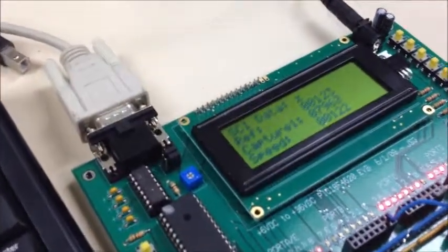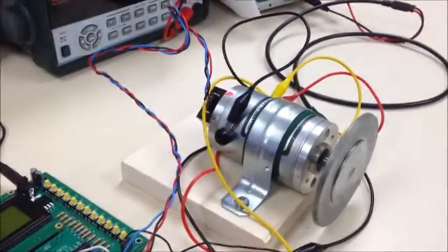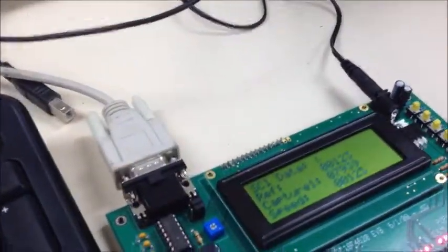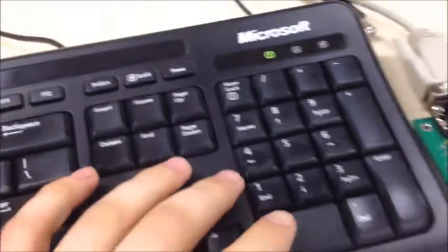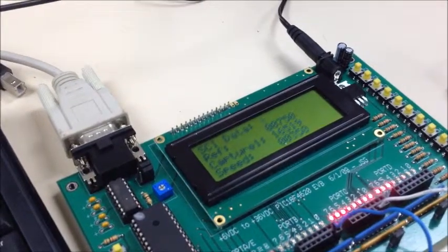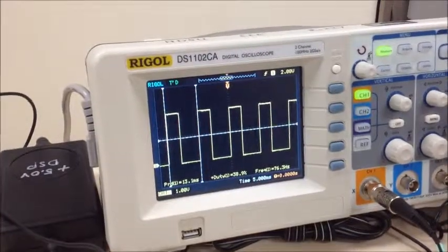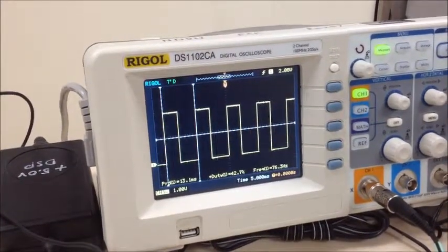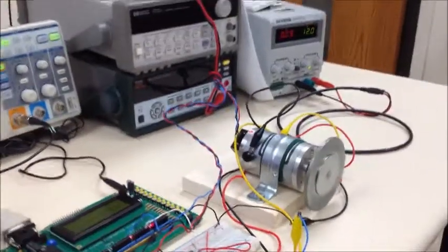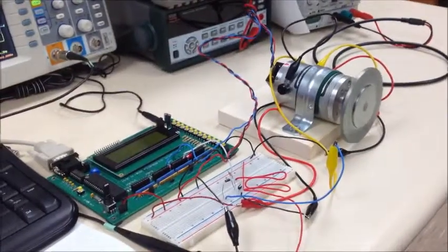So we're going at just slow speed, stable pulse width. Let's go 750. Enter the flag, and it sets the speed, which then increases the pulse width to match that speed. And using 12 volts again.